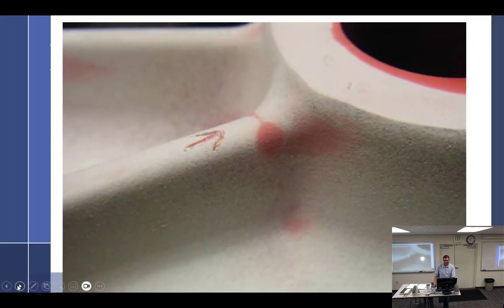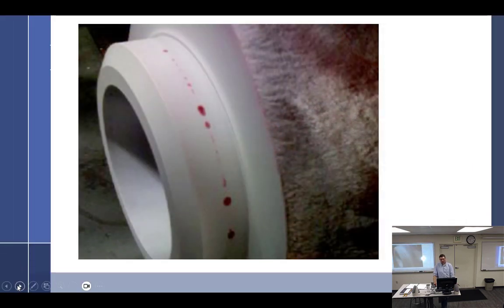Are there any repairs? I think I asked this already, but I forgot. Are there any repairs for when you find something like that on cylinders and crankcases, or is it all just scrap? I guess the answer is, for all your contemporary stuff, the answer is no, it's scrap. However, there are certified repair stations that have gone outside of the manufacturer and got FAA approval for weld repairs. So you can send it to a specialized shop who has received approval to do repairs that the factory has not authorized. How much money are you willing to spend for it? How antique is it and how irreplaceable is it?